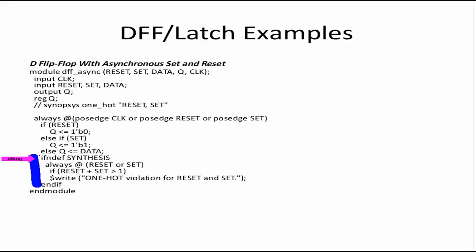But when you read the design in Design Compiler, by default this keyword synthesis is defined, and the tool will ignore this statement. This is only for simulation because you have $write and so on. This condition is checking the case where reset and set are both 1, which is an invalid case. But for Design Compiler, assume it will not do anything for that.